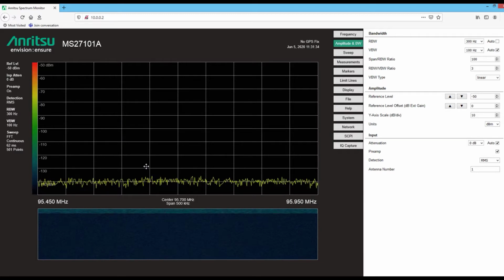So it's going to go up significantly, negative 125 or so, or maybe even a little bit higher, because of the concatenation of all that frequency together. That's why you have to make sure of how you set it up, or you're not going to have good readings no matter what you do. It's always good to be careful, because you can set things too high, reference level wise and otherwise.